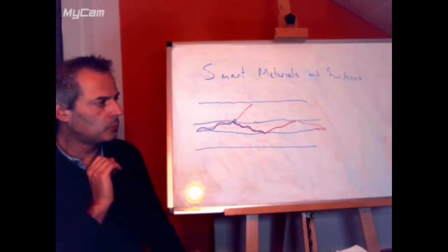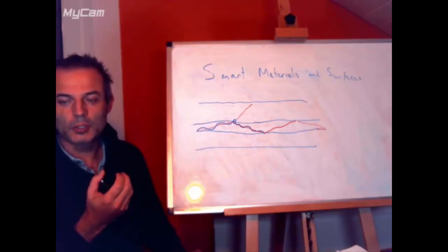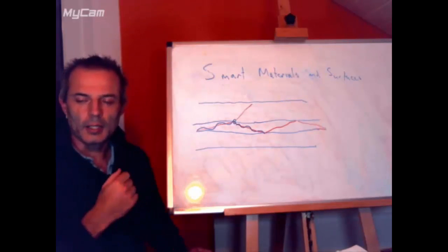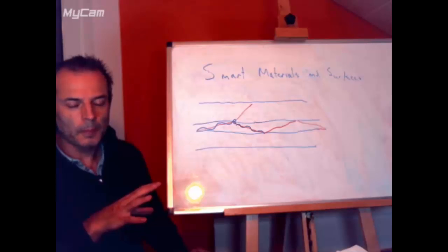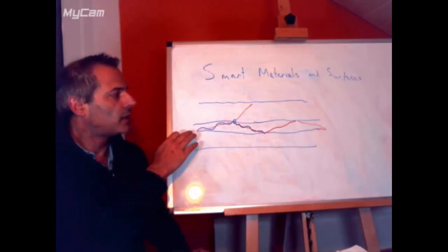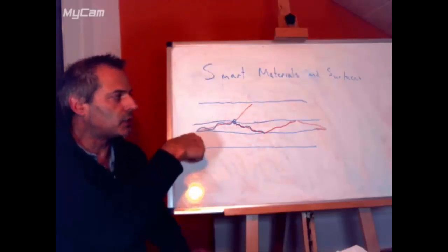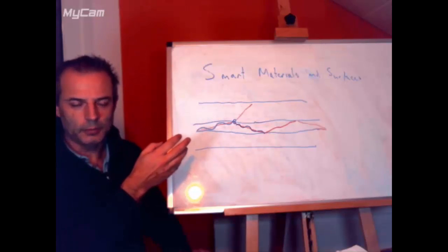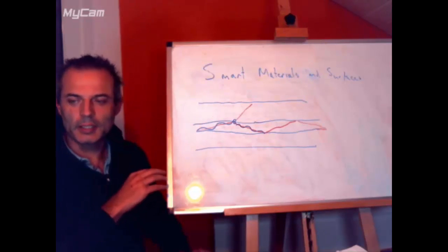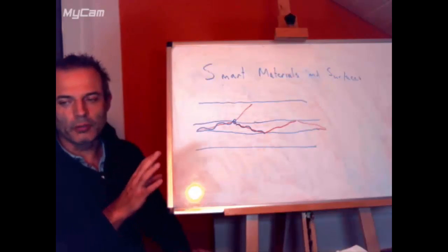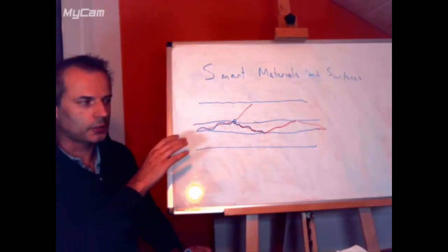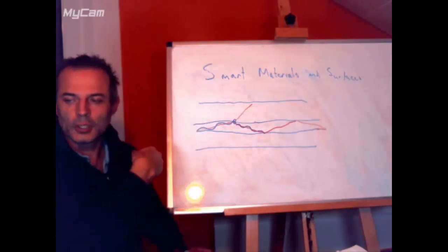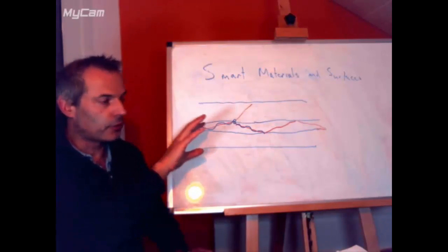That's good in this system because we could then take the optical fibers and put them into something, coat them with a chemical that changes color to some stimulus that we want, and then we can detect a change in color or a change in some property by a change in the color of the light. Even better, we could theoretically get some information as to where it is, because we don't have to put the same color on the whole length of our fiber. So we could insert a fiber and we can measure different things at different points on it.